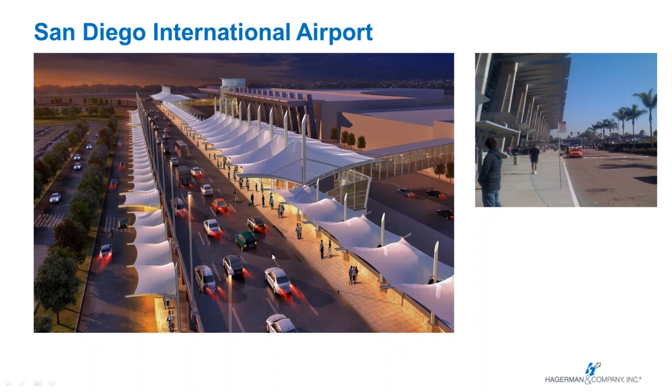One of the mandates was, if we have, let's say, a couple of shuttle buses here and some cars parked here and up here, would that air get entrained into the building? Would it be carried away? From doing this consulting study, we were able to show that the design here, because of the difference in pressure on the inside of the building to the outside, was going to make sure that nothing was going to get entrained, and so we weren't interfering with people's comfort and health.